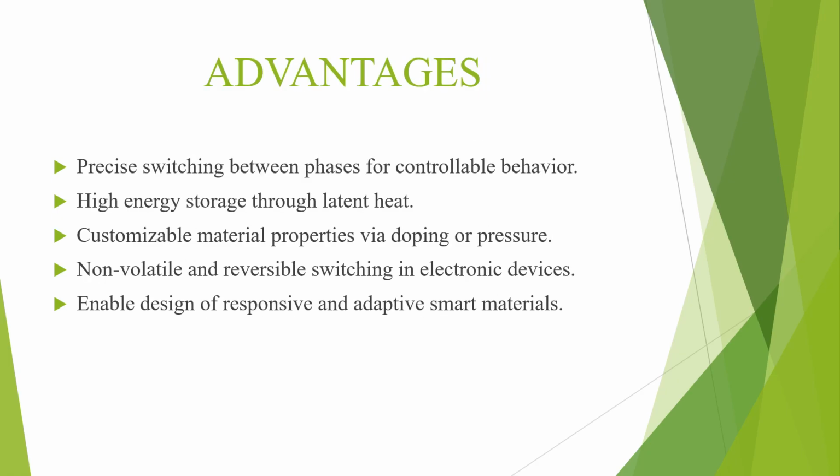Advantages: precise switching between phases for controllable behavior, high energy storage through latent heat, customizable material properties via doping or pressure, non-volatile and reversible switching in electronic devices, and it enables design of responsive and adaptive smart materials.